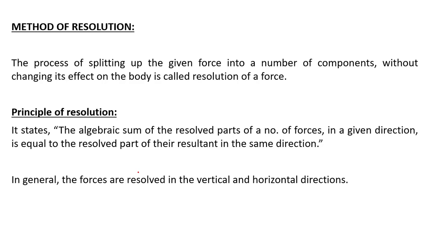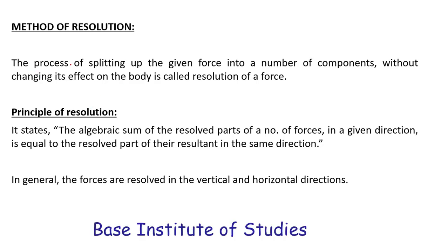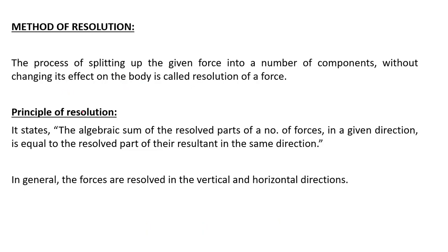So let's first discuss what is the method of resolution. What is resolution? The process of splitting up the given force into a number of components without changing its effect on the body is called resolution of a force. Principle of resolution. It states the algebraic sum of the resolved parts of a number of forces in a given direction is equal to the resolved part of their resultant in the same direction. In general, the forces are resolved in vertical and horizontal direction.